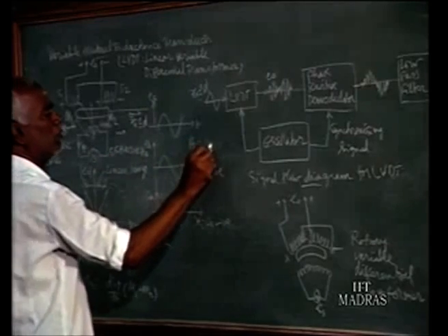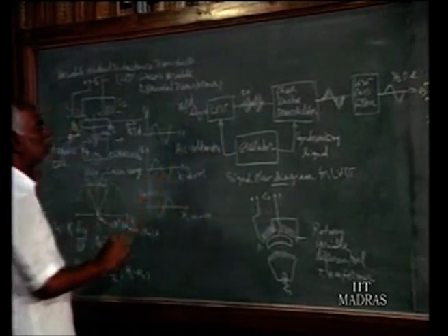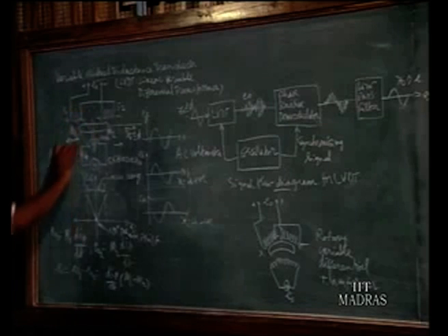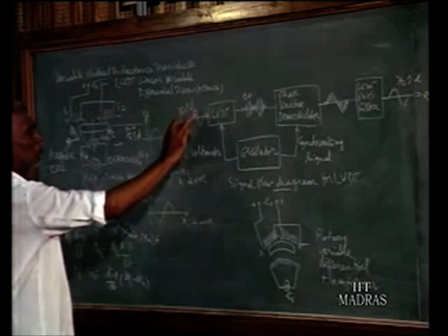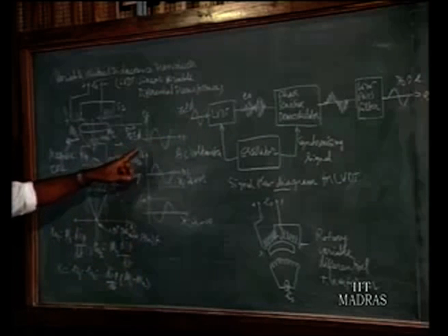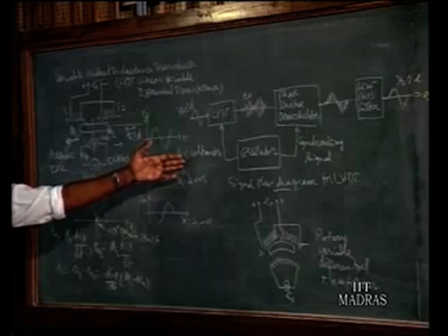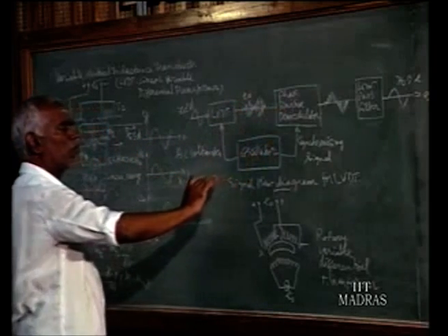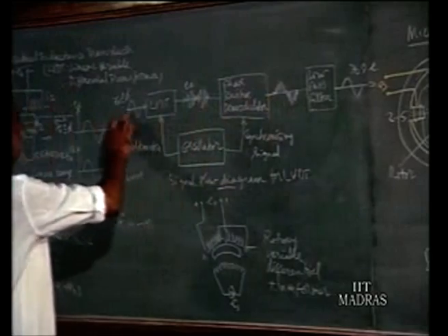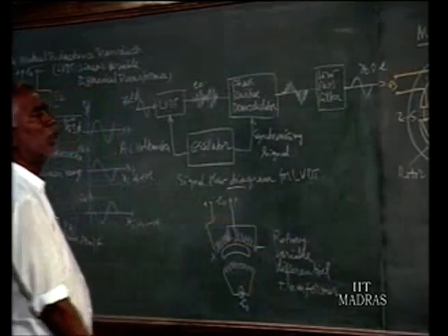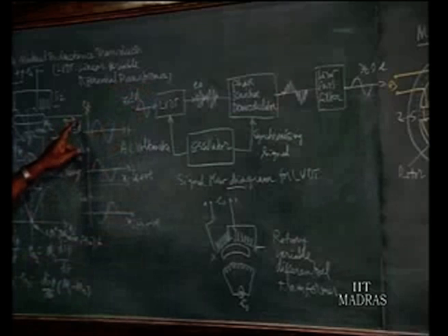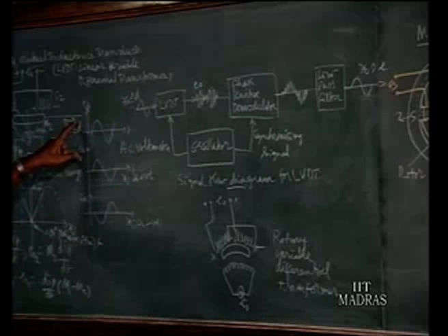In an AC voltmeter, that will give the RMS value, which is proportional to the displacement we have given. But suppose the motion takes place on both sides of the neutral position, that is, it moves to and fro like this, to the positive side and the other side also. Then if you use only an AC voltmeter, the direction will not be known. In such cases we take the EO and give it to a phase-sensitive demodulator, where again with a synchronous signal from the oscillator it brings these waves to the same side of the signal, and after a low-pass filter you get a voltage output proportional to the displacement, which can be calibrated in terms of known distances, and unknown distances can be read from the meter.